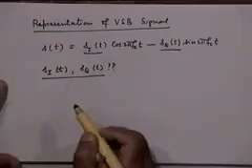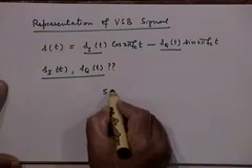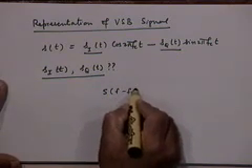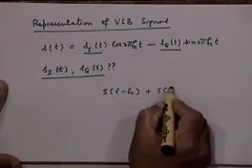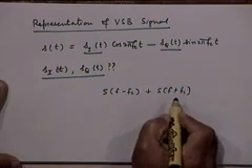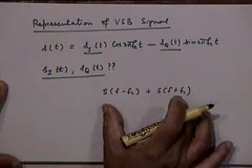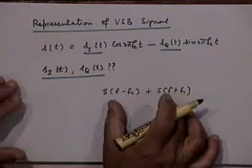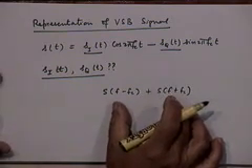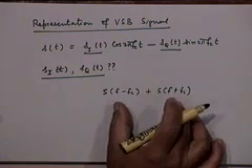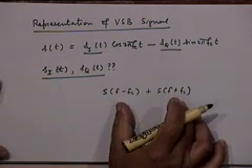So if I multiply s(t) with cosine 2 pi fc t, what is the spectrum of that signal? That will be half of S(f minus fc) plus S(f plus fc), right? And this spectrum would have a component around the baseband and a component around 2fc.